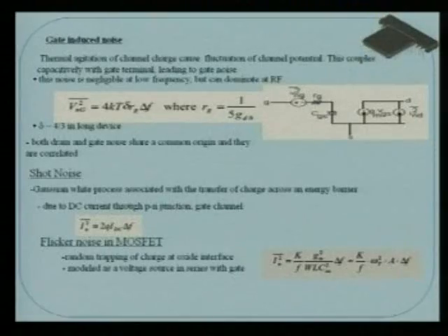If the equivalent thermal noise is equal to my gate induced noise, then I can place the series resistance at the gate, and that can serve my purpose. Instead of going into the details of the modeling part incorporated in your simulation tool, you can very well make a small signal analysis by incorporating a resistance in series. Now that is the trick, you can always use that one.